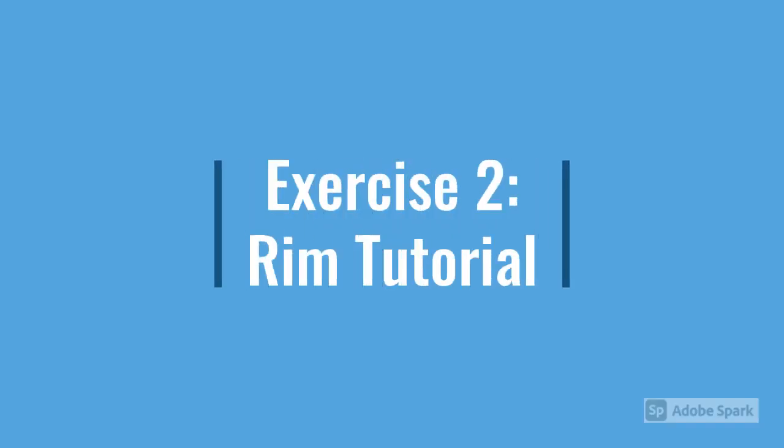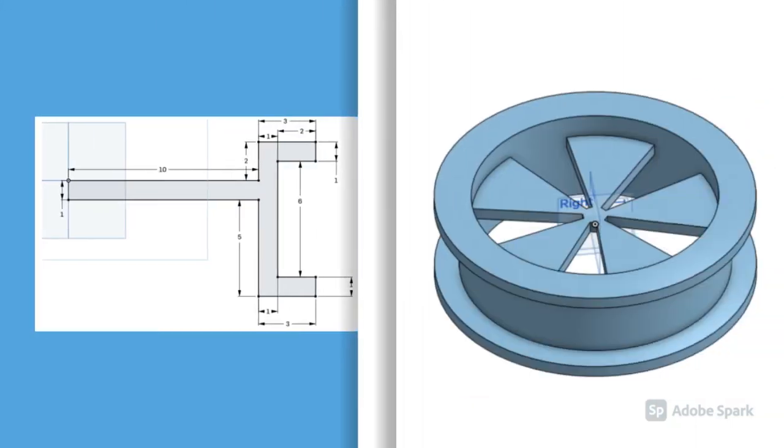Follow along with Exercise 2 to learn how you can use the Revolve tool to create a rim for a car. We'll begin by creating a 2-dimensional sketch, dimensioned like the one on the left. Then we will revolve that sketch to turn it into the rim on the right. Follow along in your own OnShape to learn how.